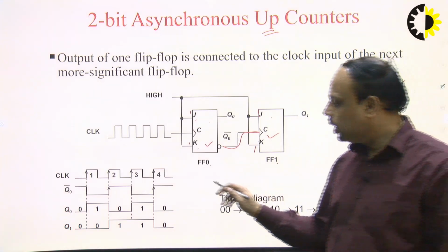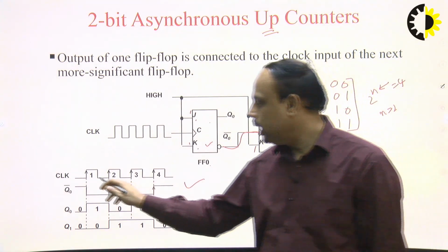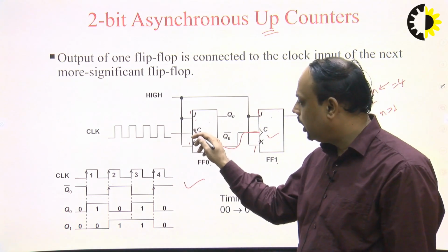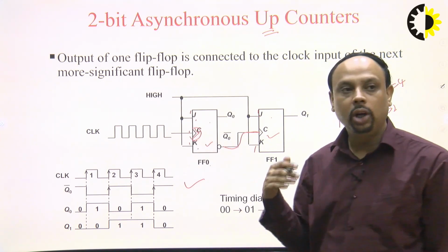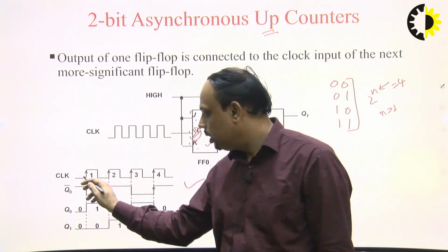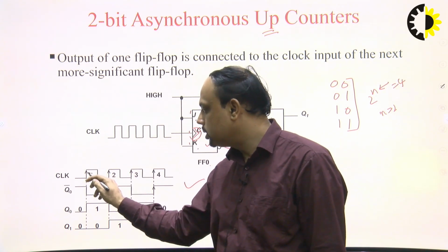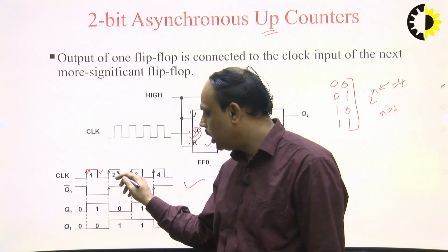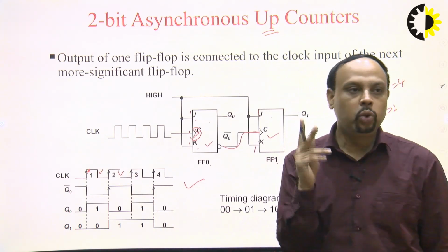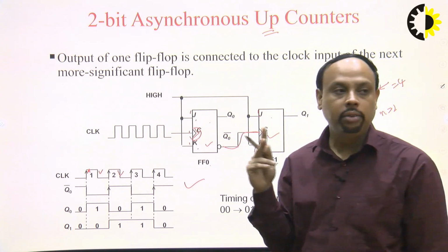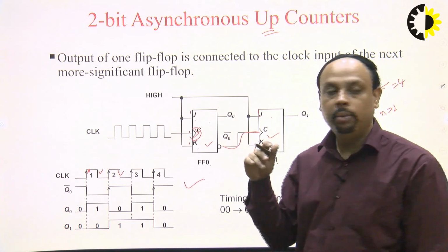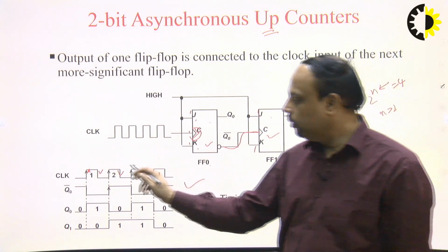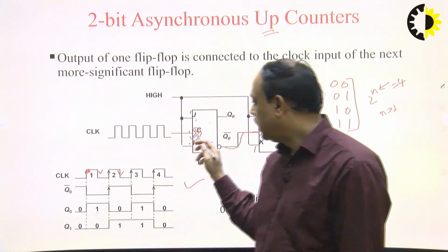Now if we see the clock diagram over here, this is the incoming clock. As this is only a triangle over here, this means that the clock is positive edge triggered. As we can see, there are 2 edges of the clock. This is the upcoming clock, positive edge, and this is the negative edge, that is going down. So we have 2 edges of the clock, and these flip flops are triggered either at the positive clock or the negative clock.